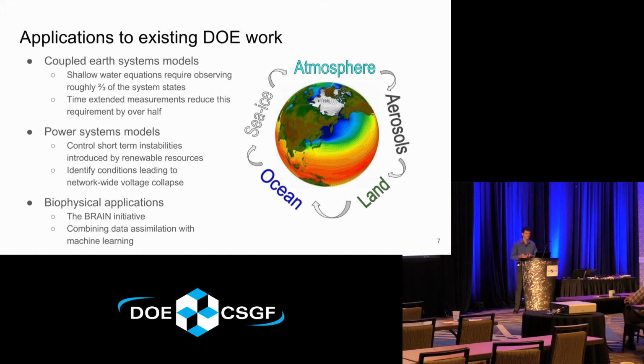However, this threshold can be reduced by over half using a 4D-Var method, and this is important when you consider that while the height of the ocean surface is easily observable using satellite altimetry, the local tangential velocities of the surface currents must be deduced using Doppler shift techniques and are therefore inherently more noisy. Furthermore, we also showed that the use of GPS trajectory recordings from drifting Argo floats, essentially buoys that float along the surface and send satellite signals back, can also further reduce this requirement on satellite coverage.